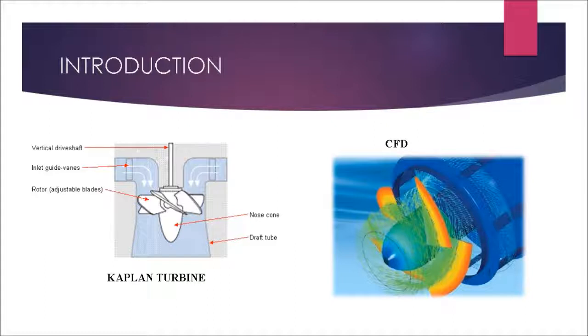The head ranges from 10 to 70 meters and the output from 5 to 200 megawatt. Runner diameters are between 2 and 11 meters. The range of turbine rotation is from 79 to 429 rpm. The CFD of the blades can be used to plot the velocity profile around the blades and thus predicting the flow rate versus efficiency graph. This can be used to design a more efficient design of the turbine without actually having to manufacture a prototype.